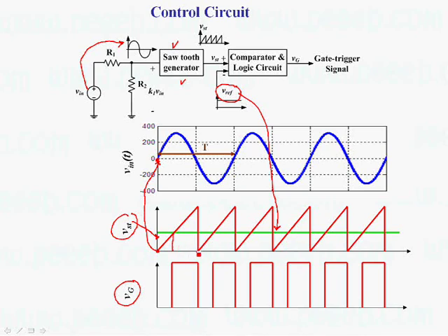So basically this time, according to the input voltage, this cycle is T/2. And suppose this time is T1 or T on. So if this is V reference, and suppose the peak of the sawtooth is V sawtooth, now we can find this time in terms of these parameters.